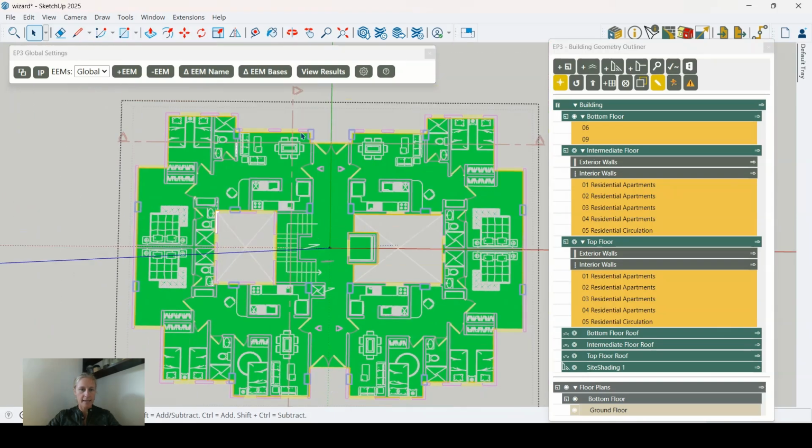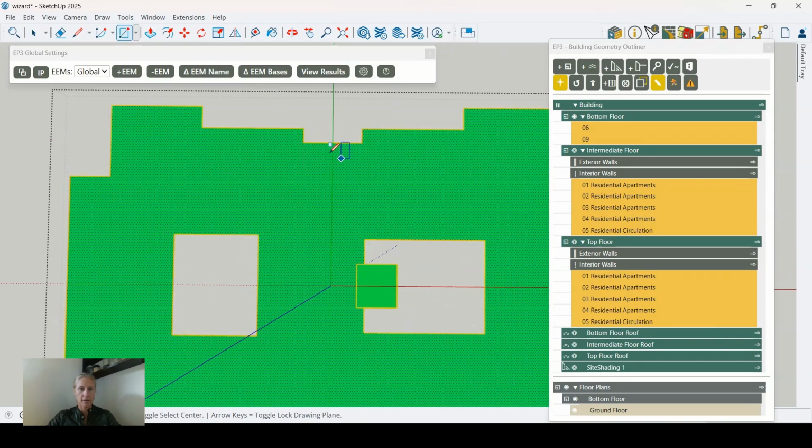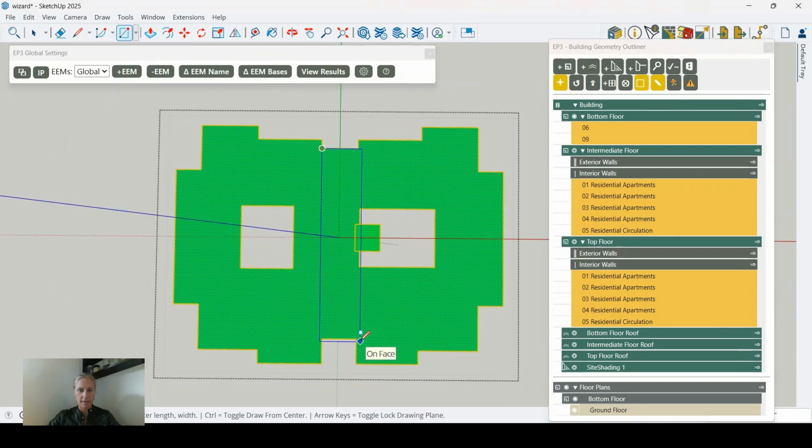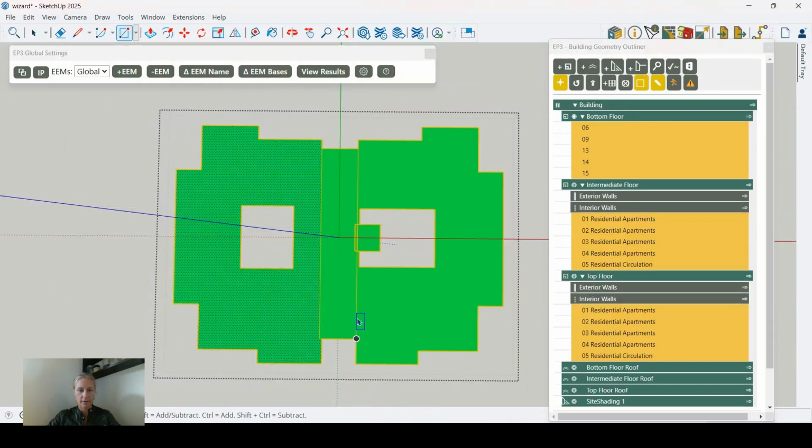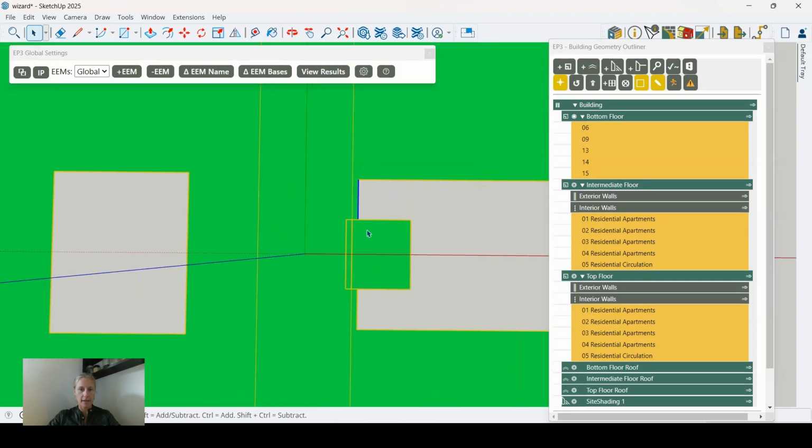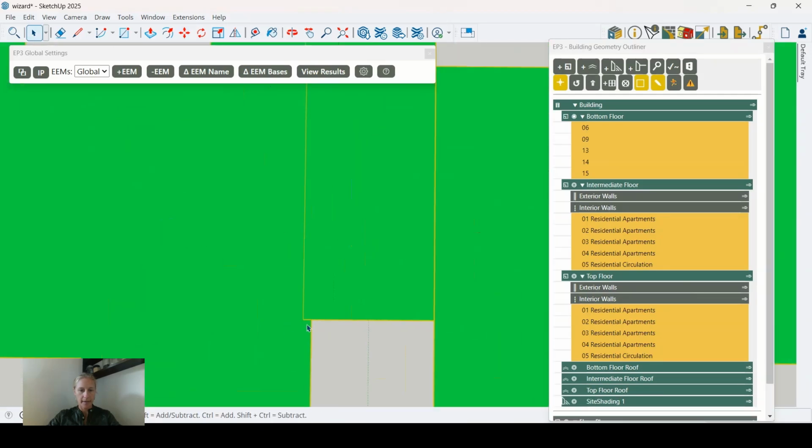And we have this center area, which is all circulation. We have the elevator and we have stairs and this hallway. So let's see, I'm going to toggle that geometry on and off. And I can just create a rectangle here. And I'm going to be a little bit OCD and just move these walls over so everything's lined up. And same down here, I'll just move this wall. M is the shortcut key for moving.